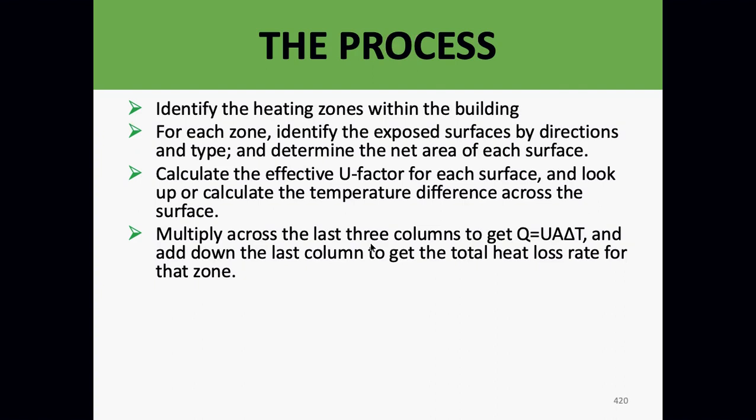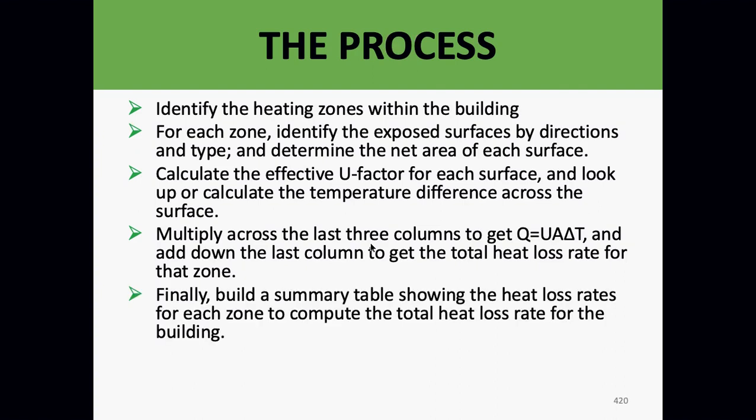Again, we're starting to get to the point where you're getting total heat loss rate for those zones. When you look down at the bottom of the column, we're just missing a couple numbers where you have a couple formulas that are not allowing you to totally finish the heat loads for each area. By the end of today, you will be able to get the total heat loss for each of the rooms.